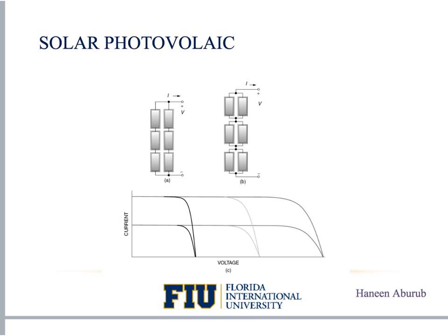The other way is that the parallel modules, as shown here, may be wired together first, and those combined in series as shown in figure B. However, we prefer the wiring of strings in parallel in figure A, because if an entire string is removed from service for some reason, the array can still deliver whatever voltage is needed by the load, because they are wired in parallel, although the current is diminished. This is not the case when a parallel group of modules is removed, as in figure B.